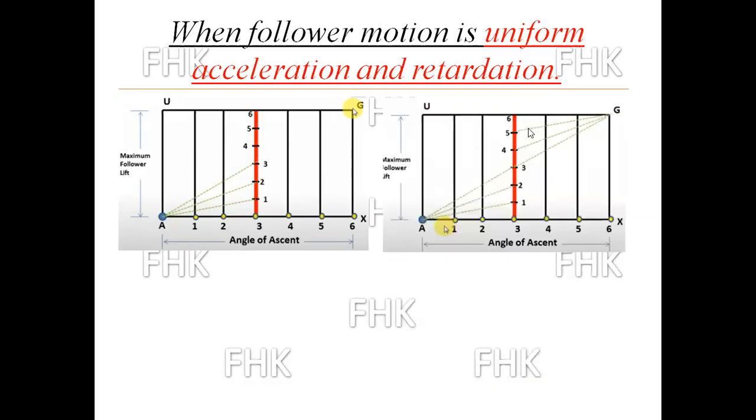Okay. Understand clearly the procedure, how I am joining the lines. A1, A2, A3 form the middle center line, which I have shown by a red line. Okay, now next G4, G5 and G6. This I will join by construction line. Now how to get the intersection point to draw the curve? This is our next step.